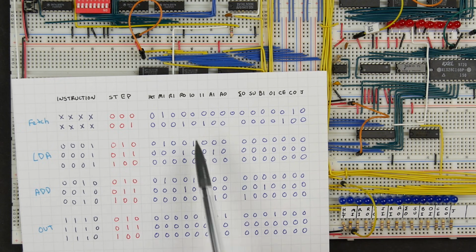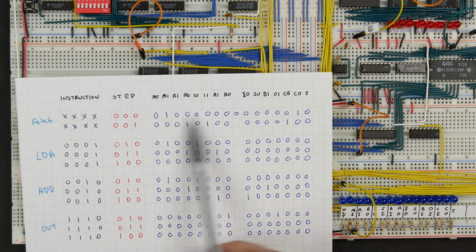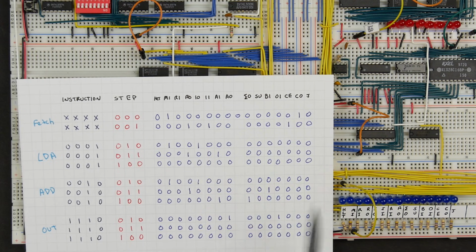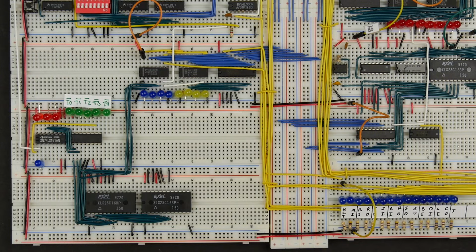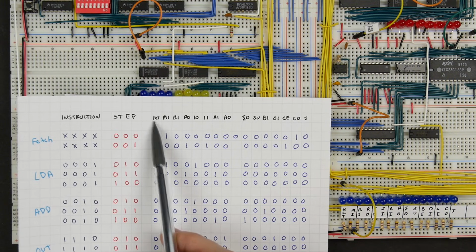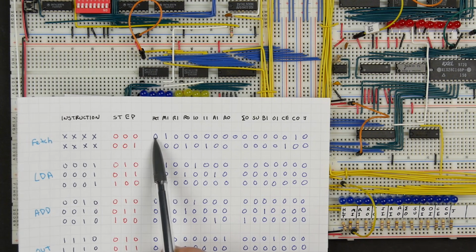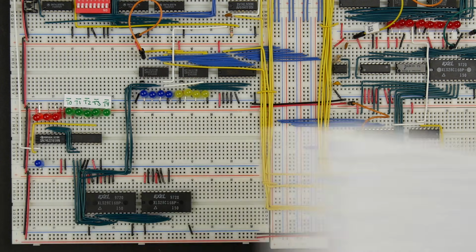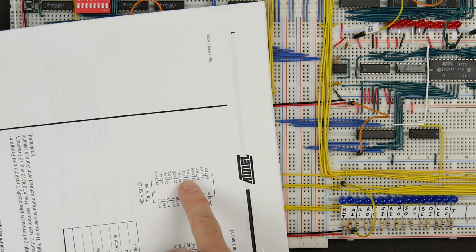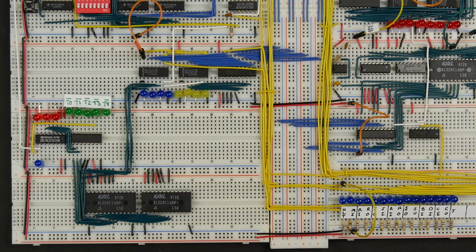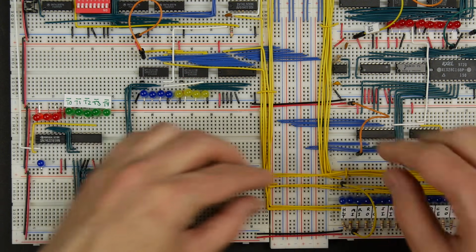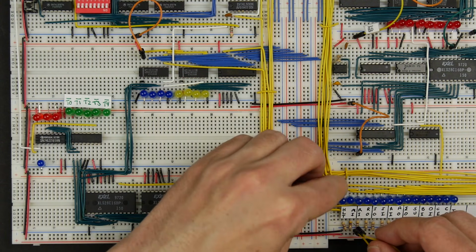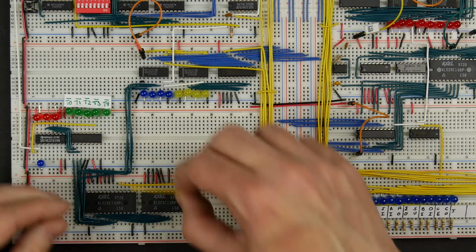And again, you can do it any order you want, but you just have to keep track of things. So I'm just going to do it the way that it's laid out here, just to preserve my sanity. And so that means halt, which is over here on the left, is going to be D7, or I/O 7, I guess. I/O 7 on the chip on the left. So I/O 7 is this pin here. So I want to connect that over to halt. So that's this pin here. And then I want to connect that to my halt signal here. And then just go down the line here.